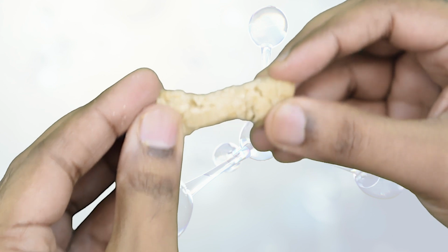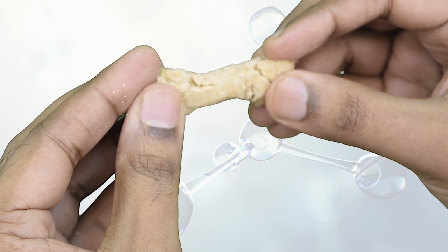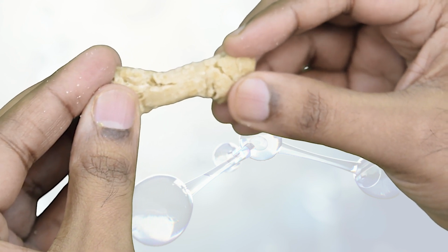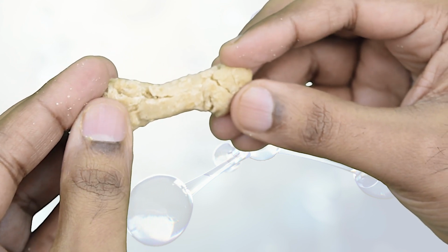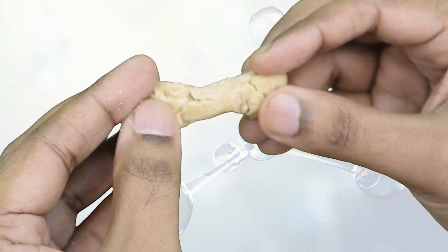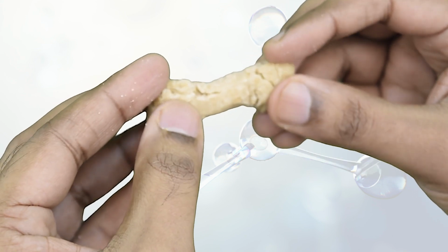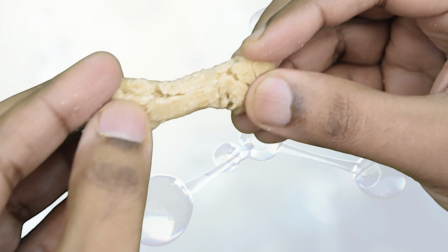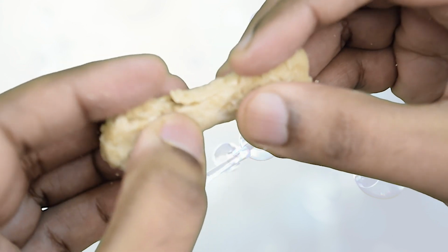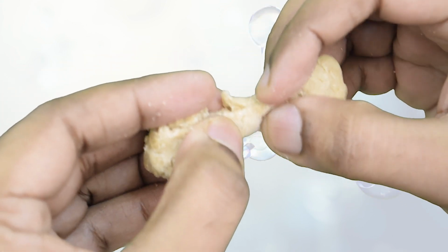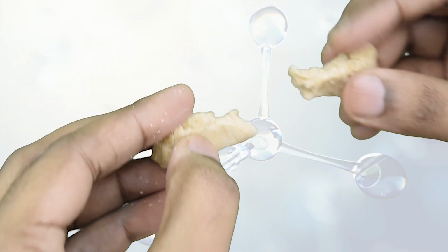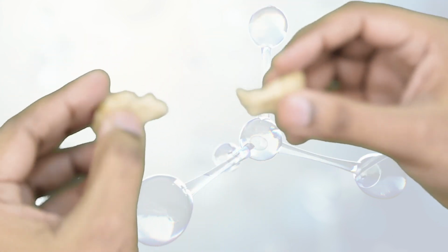I am pulling this and the stress is being acted upon this material, and you can see the diameter in the middle portion is lesser, whereas at the end portions the diameter is more, like in our tensile specimen which is placed between the machine grips. So similar to that, now I am pulling, and after pulling, necking will take place, and finally fracture. So this is the process for the steel specimen also, which is there in the machine.